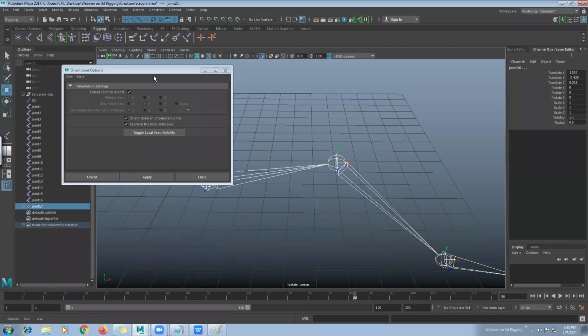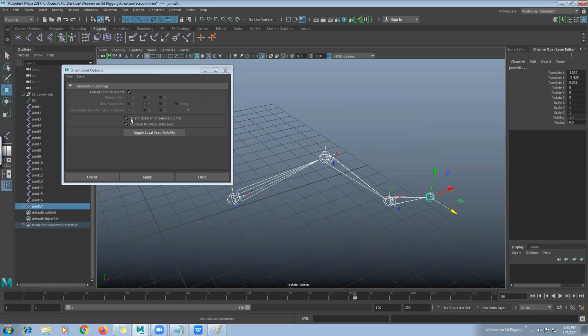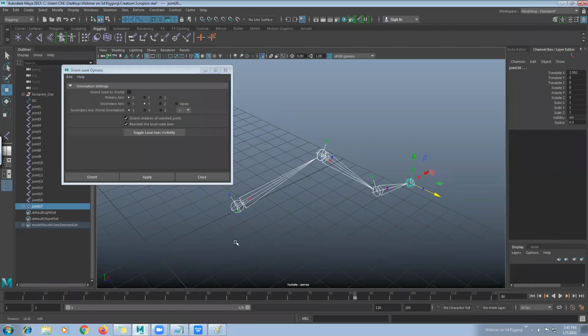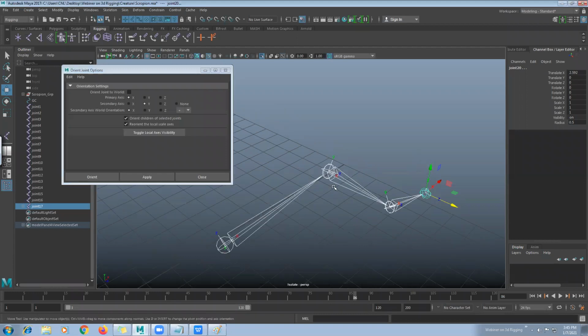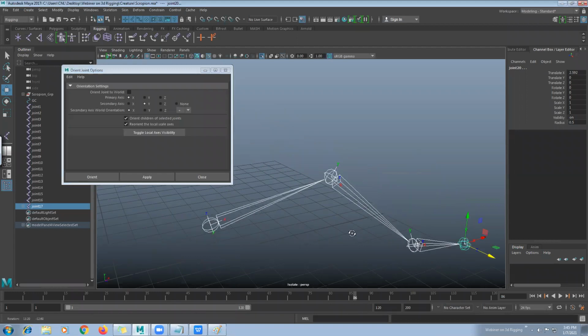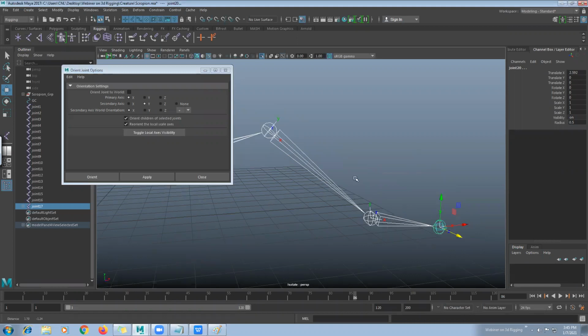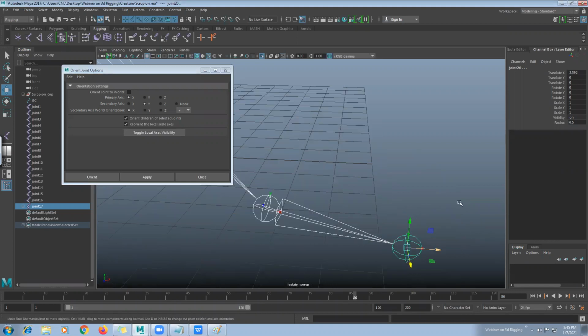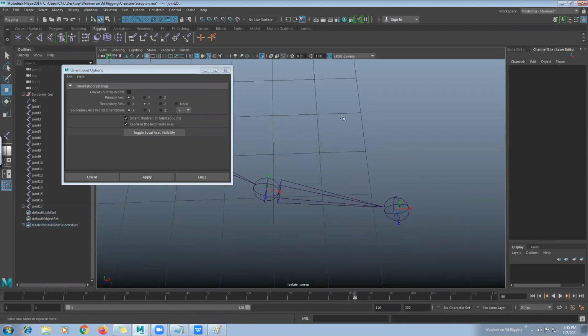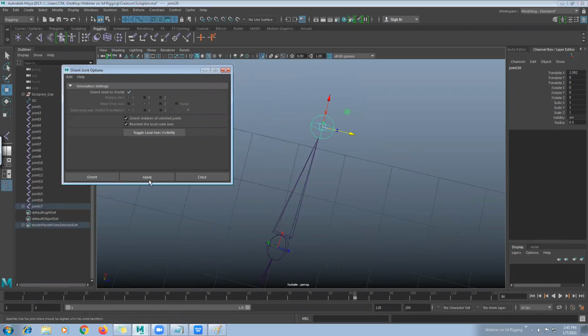So what we can do, we switch this off and hit apply first. Whenever you hit apply, you can check X is always targeting the children. This X is targeting the children. Again, there is X which is targeting the children. And this is the last child, which is targeting towards the empty node. When it is an empty node, that time you have to switch it on and hit apply once. Then it's rotated and set. Those things are very mandatory and important things that you have to always check.